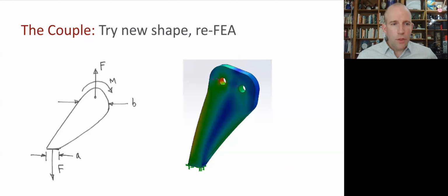And if we do that, well, one thing we'll notice is that this is going to be based on simple tensile stress. There's no moment down here, so it'll just be F over A. And up here, we'll have either combined, or if we want to say that the bending dominates, simply a cross-section that's set by the bending stress model. And because we have combined or bending stress, this cross-section will end up needing to be a little bigger.